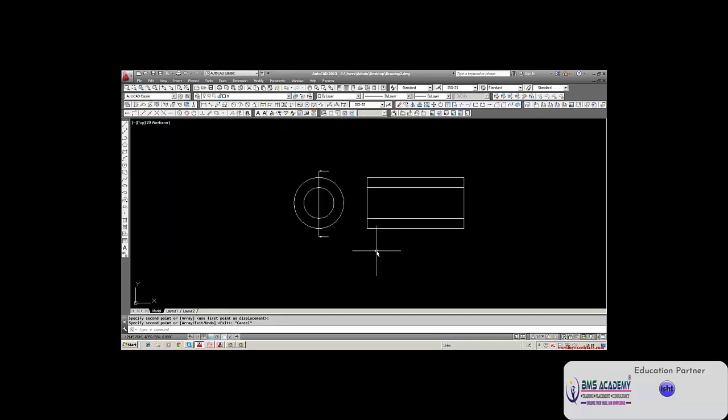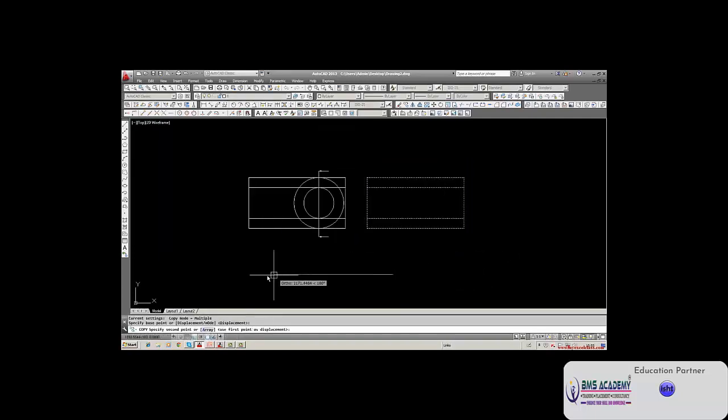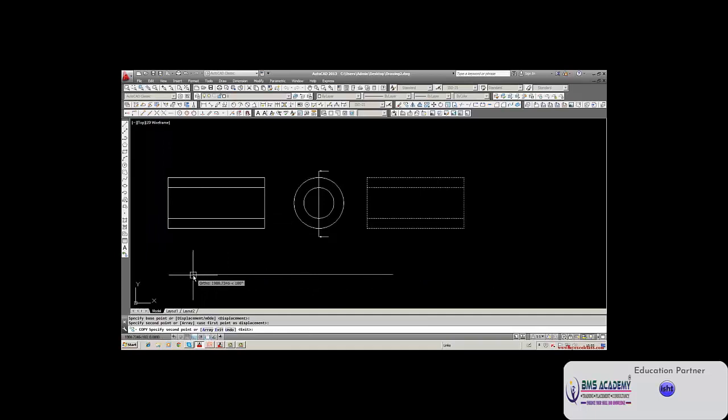Okay. And now, without cutting also, we will draw the other side. Same thing I can repeat here. See, this is the front view. If you look from this side, you will see the shaft like a circle. On that I have taken a section. In section, lines are full, so I will leave them as they are. In the front view, these lines are not visible, so we will convert them into hidden lines.